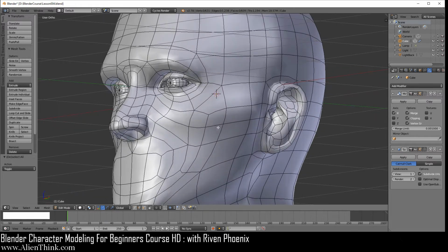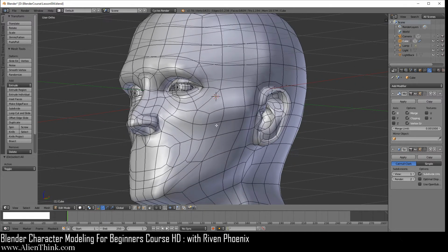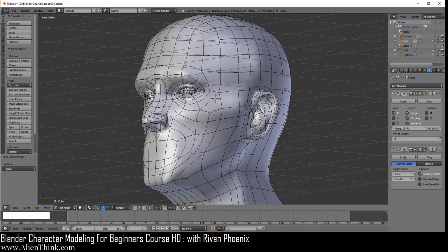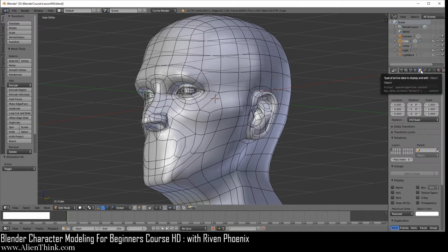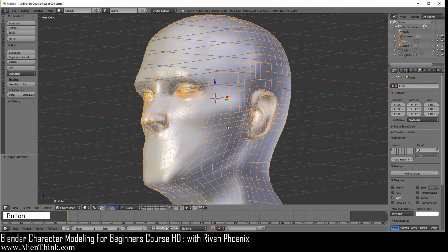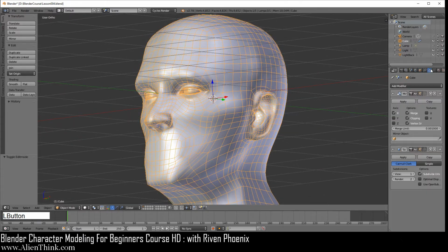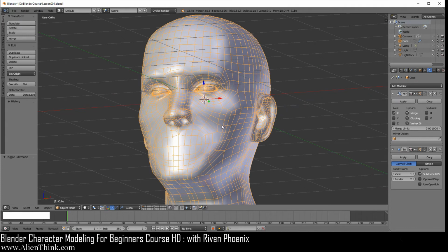You'll see that this is going to give us a three-dimensional model that is created with quads. Now, in order to see that model, you can simply click on this tab over here, then go under wire and switch to object mode. What this is showing you is that if you applied this subdivision modifier, actually clicked on this button, it will capture the model with these faces.